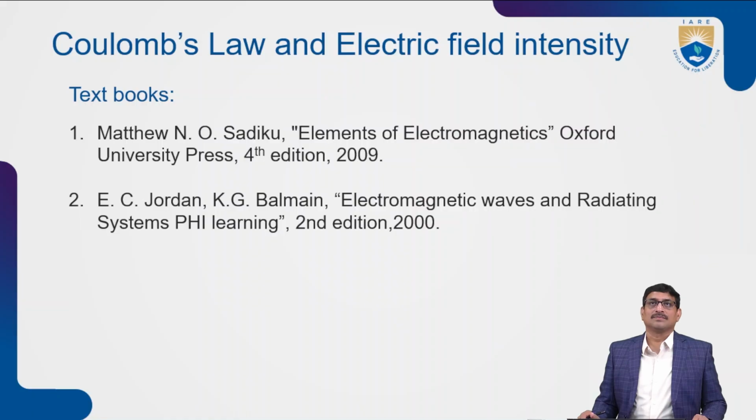We wrote them in terms of real and imaginary parts, and equated both the real and imaginary parts of those equations. We got two equations, and we put those two equations in a standardized circle form, where we varied the R values and the X values so that we got a family of constant R circles as well as a family of X circles, and the combination, or superposition, of both R and X circles together is called a Smith chart.